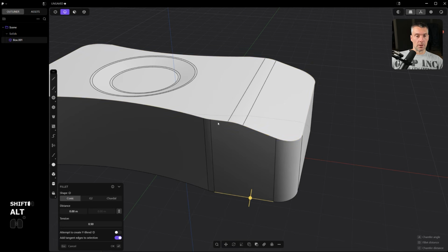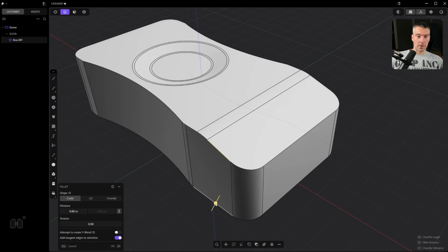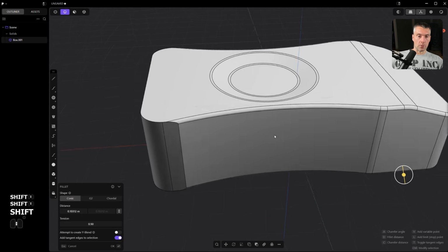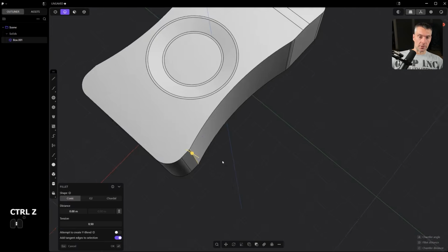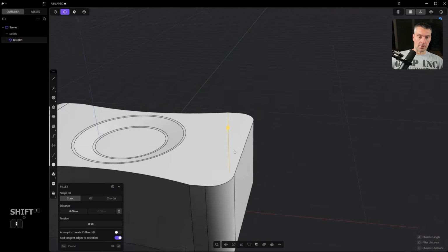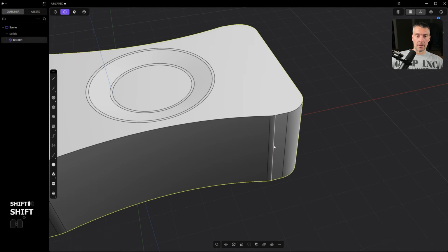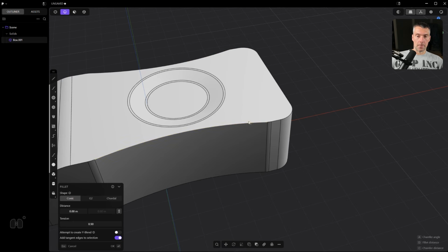You don't have to select the whole loop with Alt, just select this one and this one. It's going to intelligently continue around the shape. So bevel this a little bit. And now we're going to apply a chordal bevel. But see, we're losing a bevel here because this one is actually not beveled. So we need to bevel this. So Alt Z, bevel these two, right? So just bevel them. And now we're going to be able to probably continue across this entire shape. Let me see that. Here, there we go.